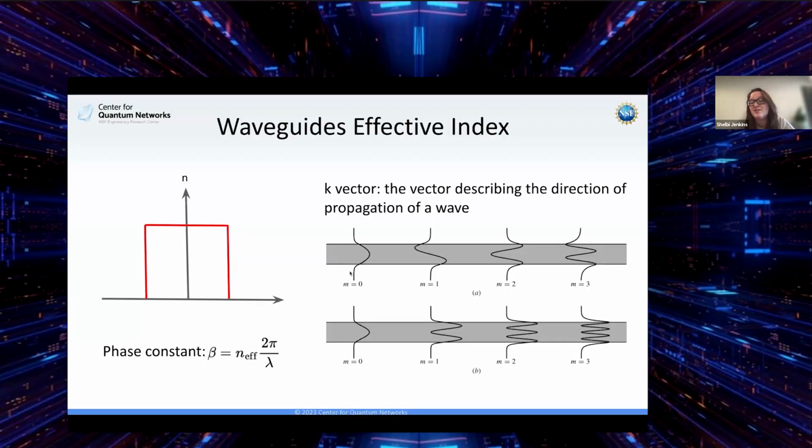What we call here the confinement factor tells you how much of the mode is confined to the core. Depending on what you're doing, you're going to want more or less confinement to your actual core material versus your cladding material. For most of the things we will talk about today, high confinement to the core is going to be preferable, but for people working in different material claddings, it might be beneficial to have more of the light interact with the cladding rather than the core.